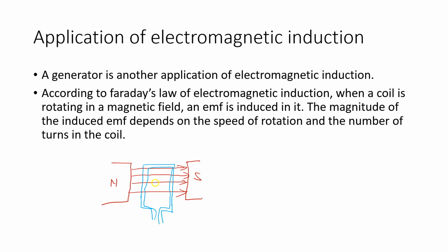you would see that having more wires would also increase the EMF, because when you look at this equation, E is equal to minus N times d psi divided by dt. In essence, the more N you have, the more E you're going to have. The faster you change this, because this is the rate of change of magnetic flux, the more E you're going to have.